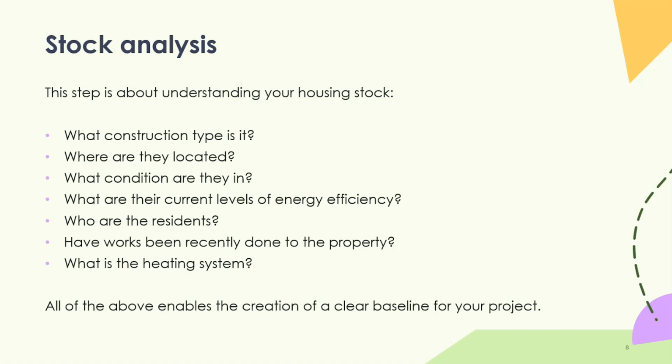Again, if you're looking to identify a retrofit program, ideally you want to find a retrofit program where you're delivering a number of houses in the same location. Again, to help allow for effective delivery, but also to help with contractors. So if you're a housing provider that has stock across the nation, you might want to look at clusters of properties where there are programs of work. So if you've got programs of EWI happening in a certain area, or if you've got blocks of flats in certain locations, so you know where scaffolding will need to be installed, understanding the location will help you understand what contractors you might need, but also what kind of measures and programs there are and how you're going to deliver it.